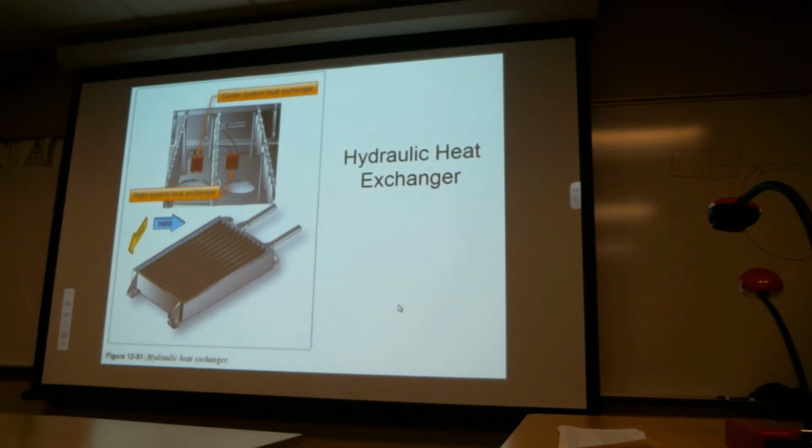Something else to consider, just using a little bit of troubleshooting information. You're doing some hydraulic fluid sampling, and you notice what you get back as a result after sampling: the hydraulic fluid is contaminated with fuel. Where do you suppose your leak might be? It's in the fuel tank. It's in the heat exchanger. Very good. Okay.